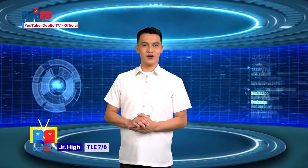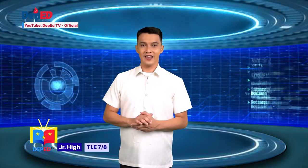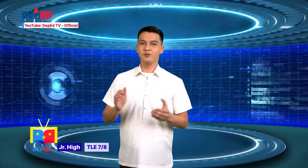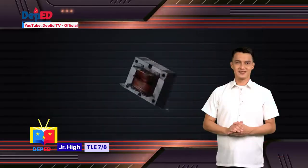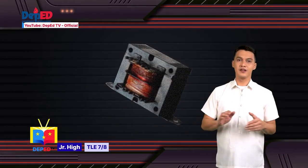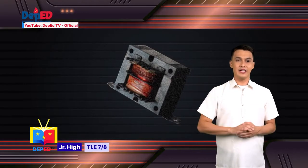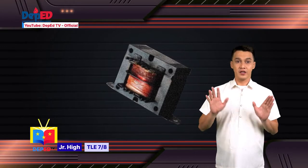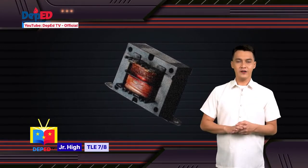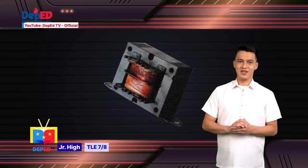An open secondary winding will prevent the flow of secondary current, and once again, no voltage will be present across the load. A partial or complete short circuit in the primary or secondary winding of the transformer will result in an excessive source current that will probably result in the overheating of the transformer, which could lead to it being burnt.